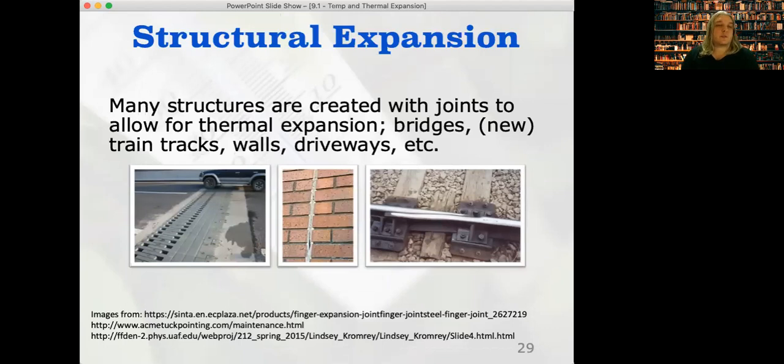You'll also see on bridges that they usually have a tooth, tongue and groove, or a tooth type setup, as per that first photograph, and that's again to allow for that expansion. Because bridges are usually a set length, you know the maximum it could possibly expand, so you can allow for that. Because train tracks get so long, that's why we need the room for unlimited expansion by going past next to it. Not as much of a problem with bridges, because they can't really get unlimited expansion. They're a fixed length, they can only get a certain amount longer.